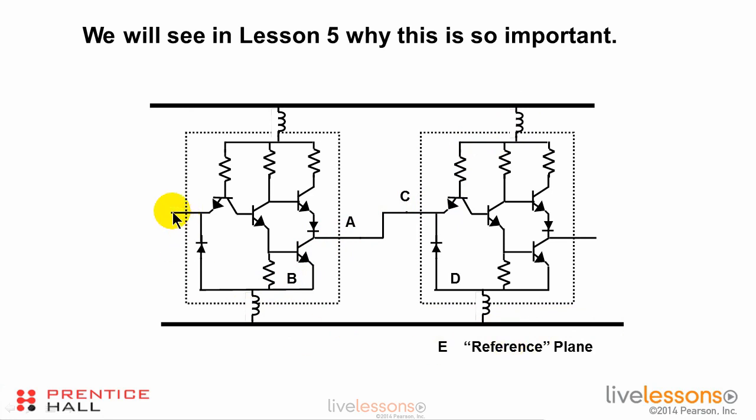Now, if this switches very quickly from, say, a logical 0 to a logical 1, then this is going to switch very quickly from a logical 1 to a logical 0. We're going to dump current very quickly across this inductor. And let's just say the specified voltage between A and B for a logical 0 is 0 volts. Now, it'll be slightly more than that, but for convenience and for discussion purposes here, let's just say that would be 0 volts.